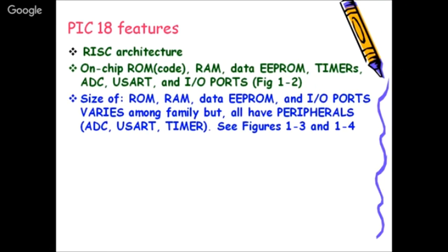And of course, on-chip code memory is available up to 128 kilobytes in case of PIC 18, but it has a scalability up to 2 megabytes. And when it comes to developing embedded systems, this matters, that how much memory we can connect to the particular controller, unlike your general purpose x86 based embedded system, wherein you have all the flexibility of adding as many blocks as you want. But in case of microcontrollers, you have limitations that once you select, it remains fixed. So if you select a PIC 18 family, your ROM can go up to 2 megabytes because of the inherent capabilities.